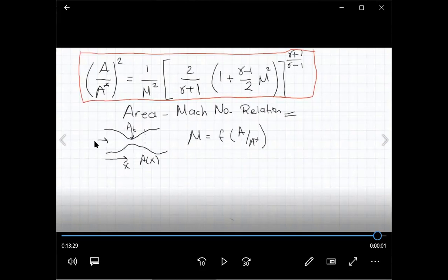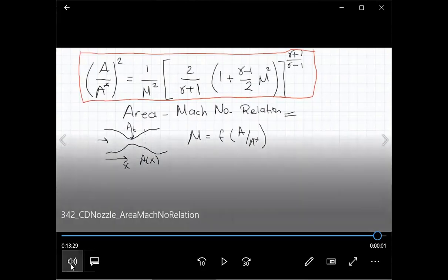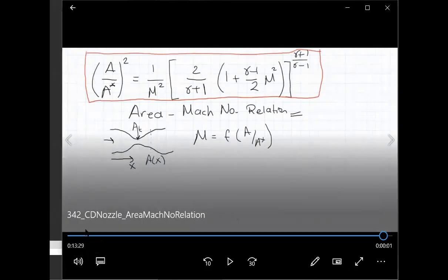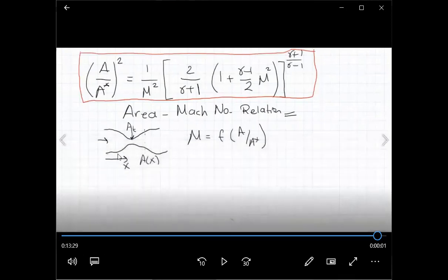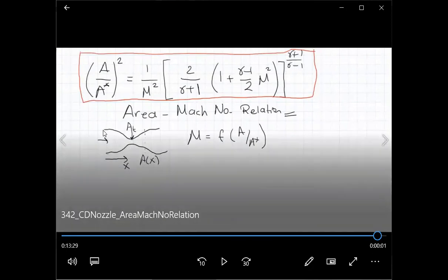Okay. Hocam, how do you decide on the length of the subsonic part and the supersonic part? The length is not that relevant in this stage. The important thing is area variation, because we are dealing with quasi one-dimensional flow, but of course the length is related to the shape of the nozzle. As you see, it does have some kind of a curved shape.